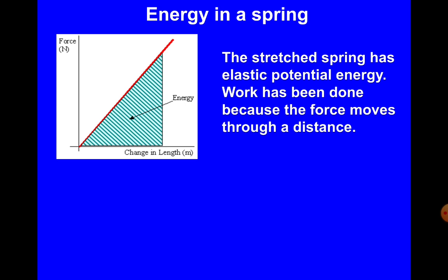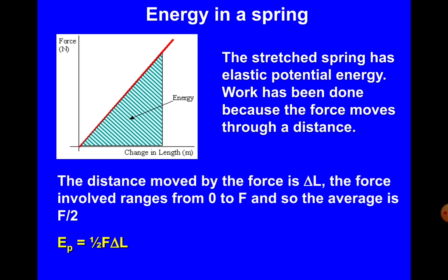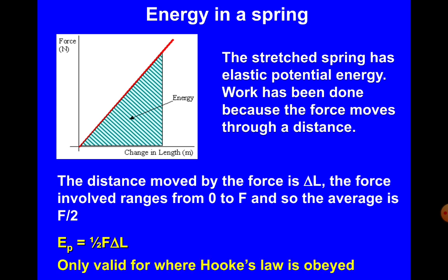And this is actually an elastic potential energy because work has been done as the force moves through the distance. So the energy that is stored, and this is a triangle, is then half times F times delta L. Obviously, we can only use this when Hooke's law is obeyed.